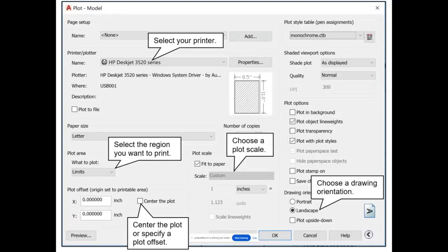Isn't it great? So what I came up with is, you know what? For the most part, we create PDF files of things that we want to share with other people. We don't technically print them out per se, and if we wanted to, we could print out the PDF just as easily. So to keep AutoCAD from screwing around with our title block and stuff on our layouts, if you set it to a PDF file that I'll show you, it works better.